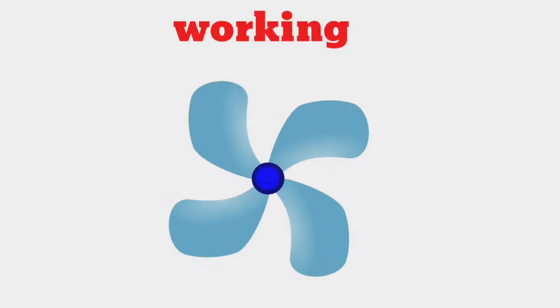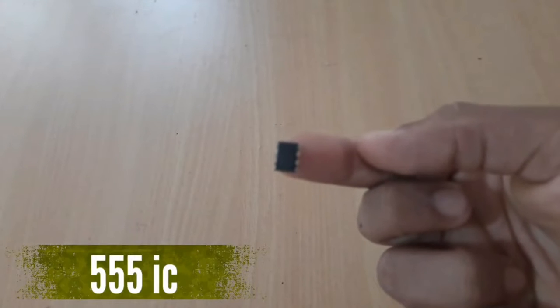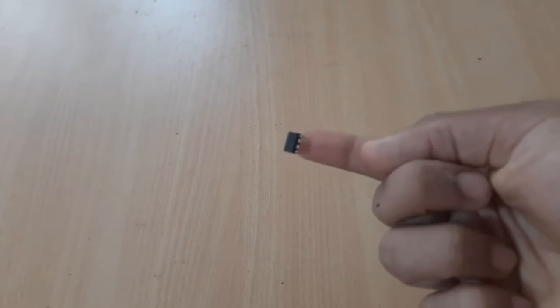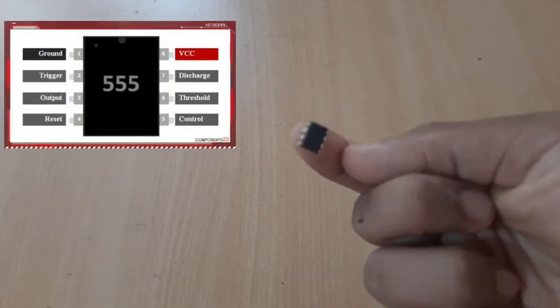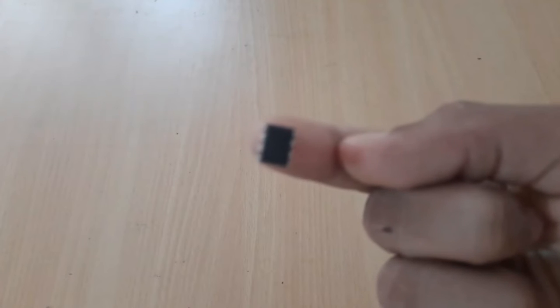The next step is to build a circuit. For generating such a frequency, I decided to use a 555 IC. For adjusting the frequency, I used a 10K potentiometer with the 555 IC. The list of all components is in the description. Then I designed the circuit. Let's understand how the circuit works.